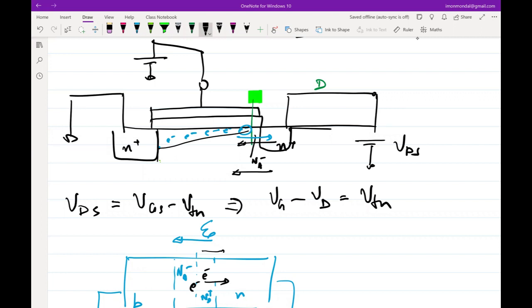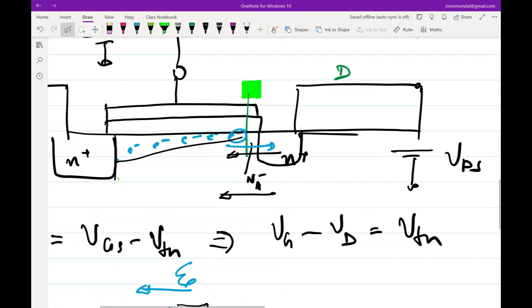It would not increase the current. Okay, yeah. So let me get back to that. So essentially what is happening is, even before going there, let's assume that this depletion region is of finite width, right? So this pinch off region is of finite width. Let's call it del X, or let's call it del L, because this horizontal dimension we call L, so let's call it del L.